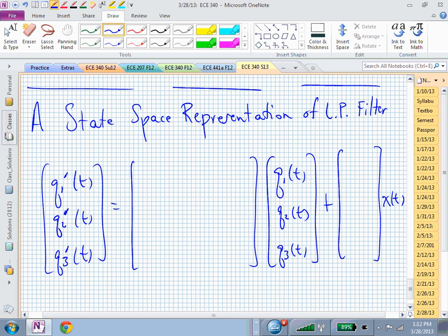If I gave you 10 integrators in a block diagram and I ask you what's the dimension of A, you're going to tell me, aren't you? 10 by 10. If that 10 integrator block diagram had 3 distinct inputs, what's the dimension of the input matrix B? It's 10 rows tall, 3 columns wide. It's 10 by 3. All right, so let's now fill this in from memory.